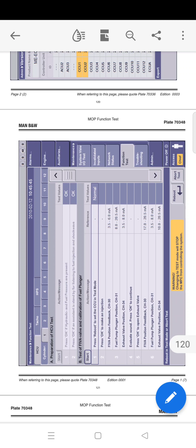For testing the fuel injection components, the FIVA will make one fuel injection. This is verified by the assistant on the engine top by feeling the shock wave on the respective fuel injection pipe. For testing the exhaust valve components, the FIVA will activate the respective exhaust valve once. This is verified by the assistant by listening for the thump sound of the exhaust valve opening and closing.